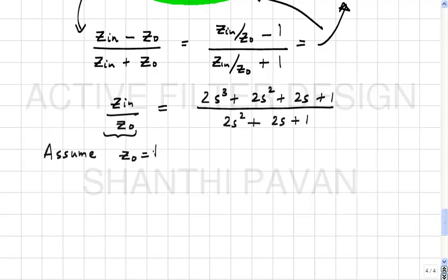You just have to scale all impedances up by that number Z0. Whatever values for L and C you get here, for an arbitrary value of Z0, L will get multiplied by Z0 and C will get divided by Z0, so that all the impedances have been scaled by the same factor.